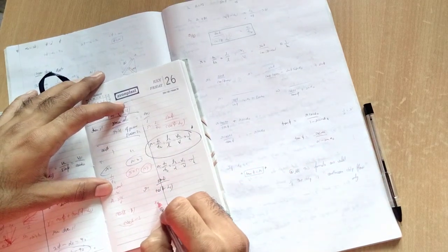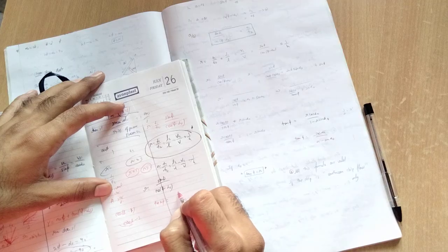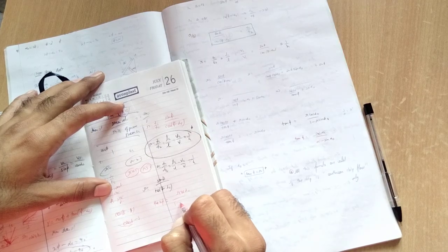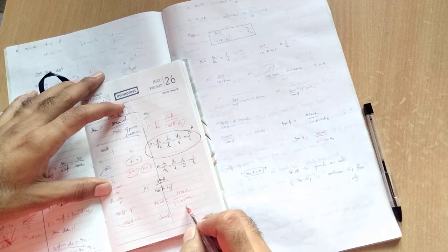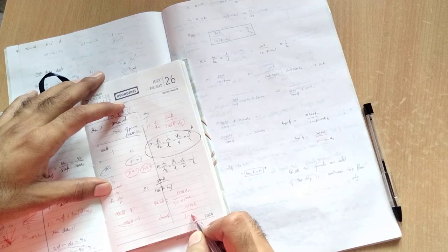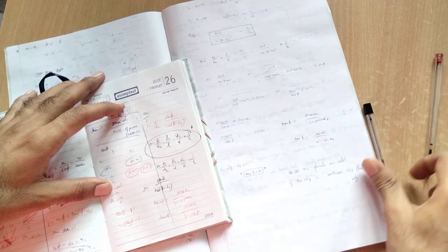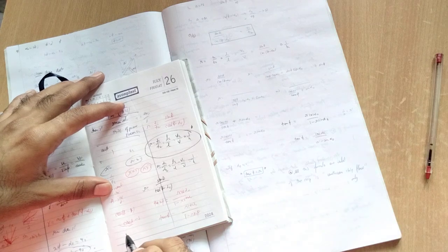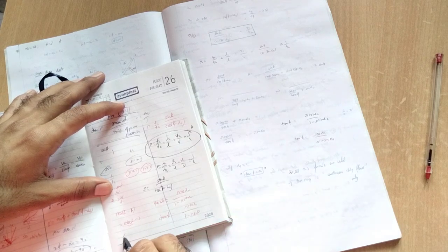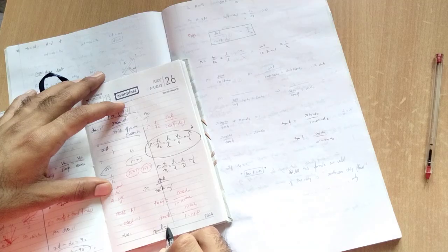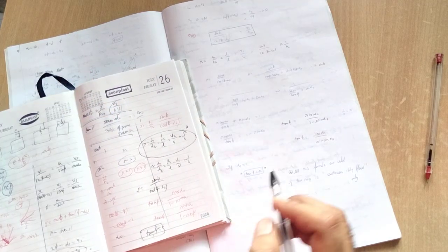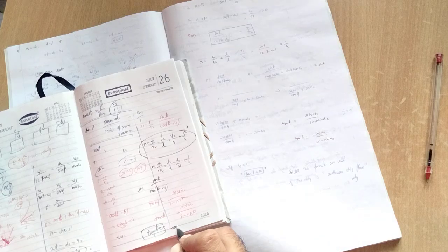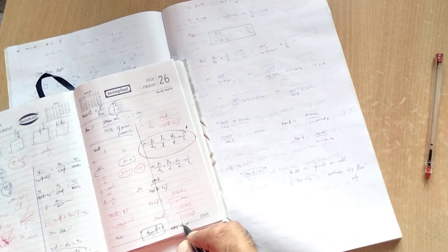So next, tan of shear angle equals R cos alpha naught divided by 1 minus R sin alpha naught. This is also one of the most important ones. Whenever alpha naught, the back rake angle, tends to 0, you can see tan of shear angle equals R. I think you can understand. This formula is only for continuous chip flow only.